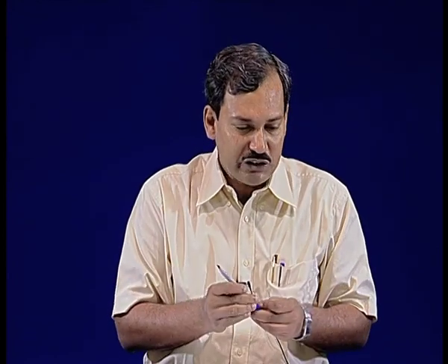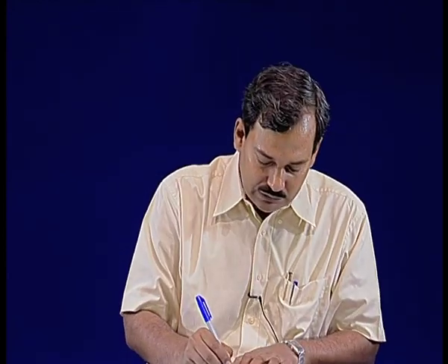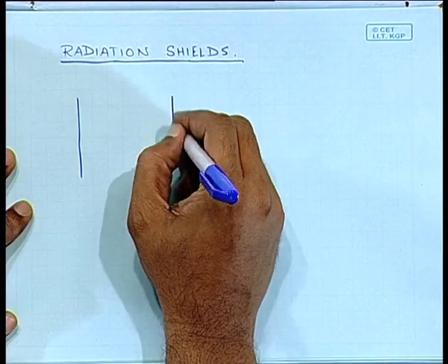All right, and when I write those resistances in terms of emissivities and view factors, then you would see that you would require some specific value of those emissivities. Would it be very high emissivity or low emissivity? That's what we are going to find out. The rest, there are no new concepts involved. It's simply we are placing a number of shields in between two surfaces to reduce the heat that's coming to another surface. So a radiation shield is nothing but we have two surfaces.